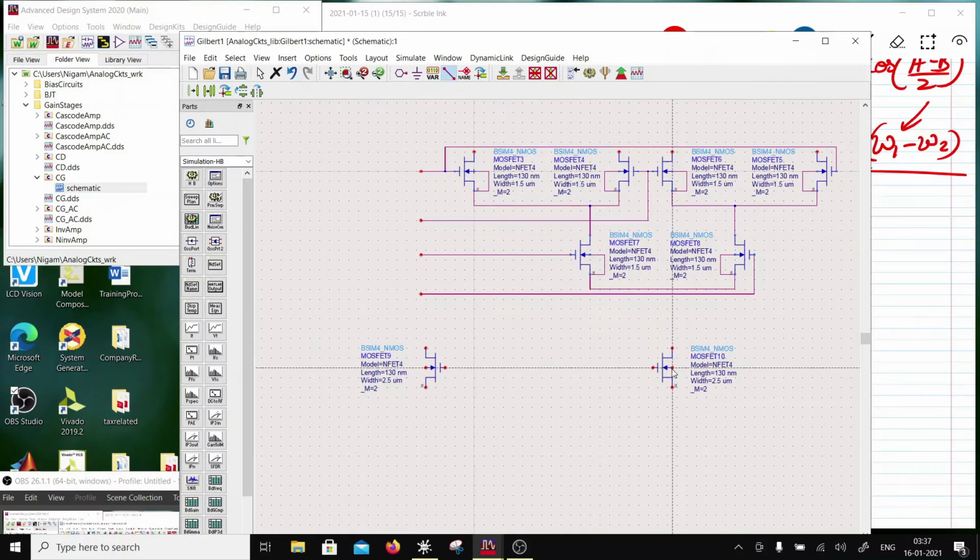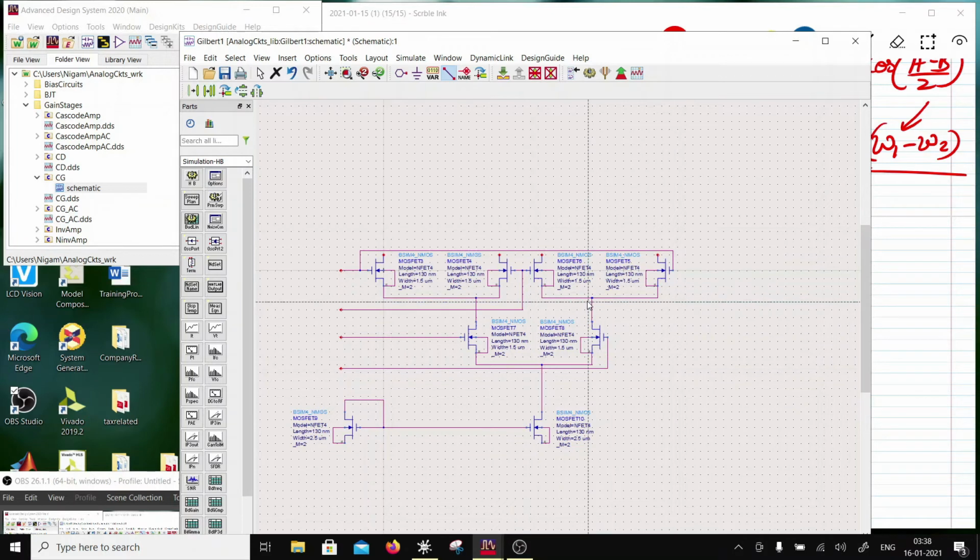The next thing I'm going to do is the diode connection, the body connection here to its source, and this is a diode connected transistor. And this is pulling out the tail current from here. So we are all set with the design, only we have to put resistive load here. So I'm going to put 2.5k.